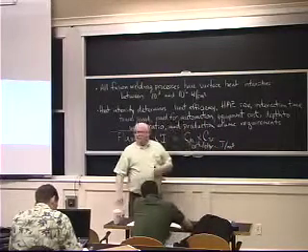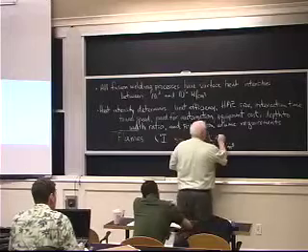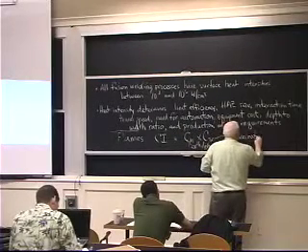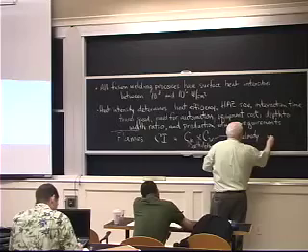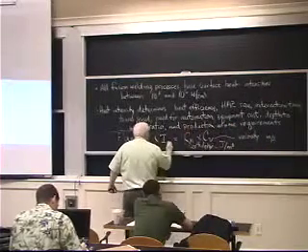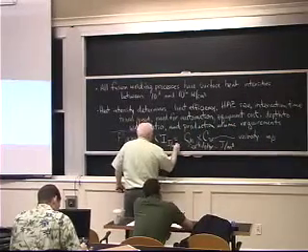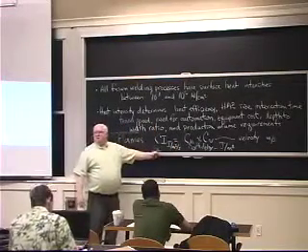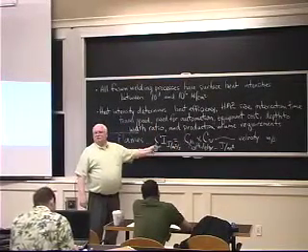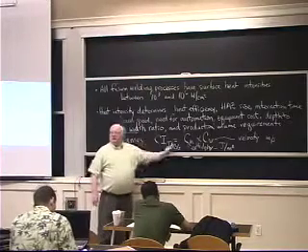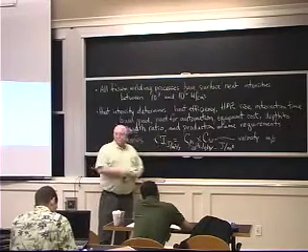And there's also the combustion velocity, and that has units of meters per second. If I multiply all this together, I get joules per meter squared per second. Anybody know what units those are? Watts per square meter, which is sort of like watts per square centimeter. If you go to the flames business, they talk about combustion intensity. Now you have to be careful.